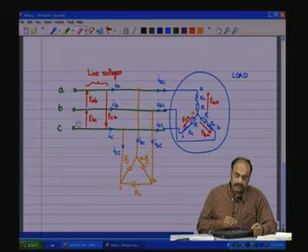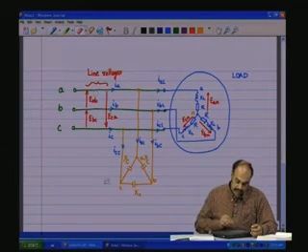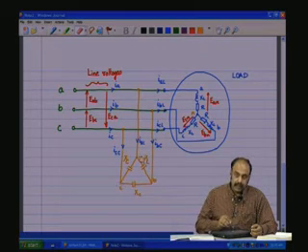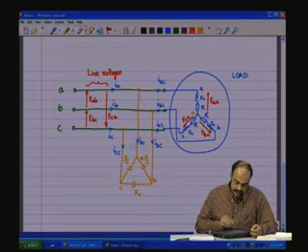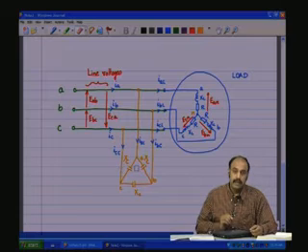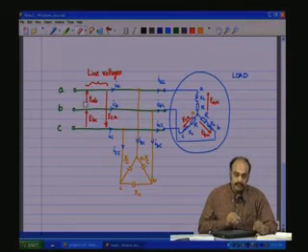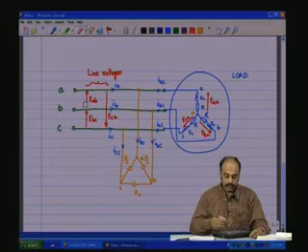Therefore, to compensate for the reactive component, so that it can be delivered to this buffer capacitance and taken again as and when required, the capacitive reactive network as shown here is generally used, so that the power factor as seen from the source side is improved. That will become evident once you look at the phasor diagram.